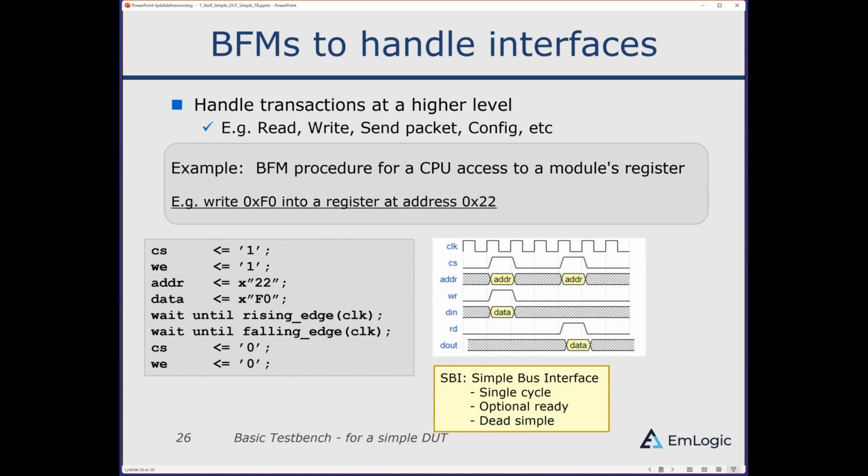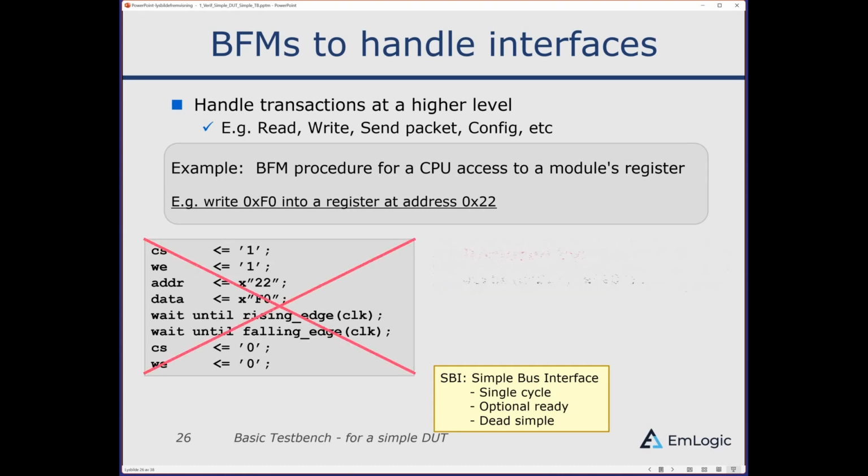So what we need is these procedures, the BFMs, bus functional models. So what is a bus functional model? That is basically a procedure in VHDL that allows us to handle transactions at a higher level. So it could be to write, to read, to send a packet, to do some configuration, or whatever.